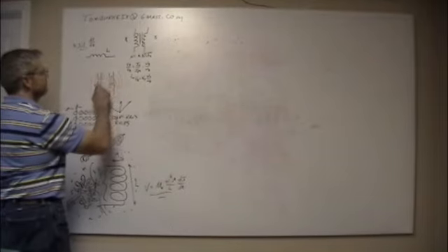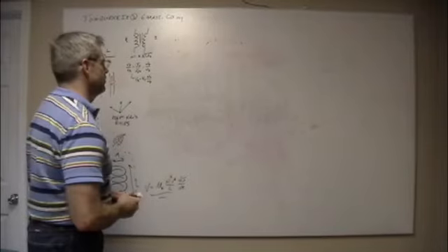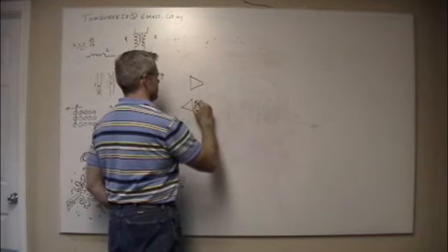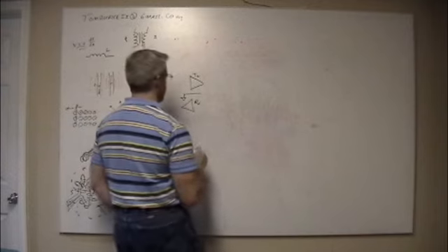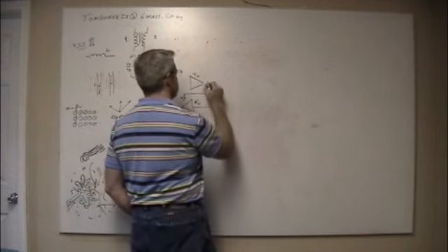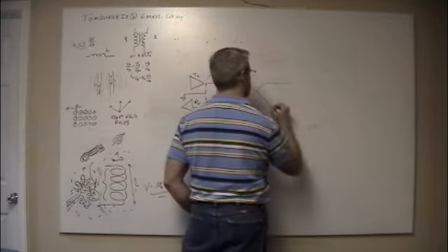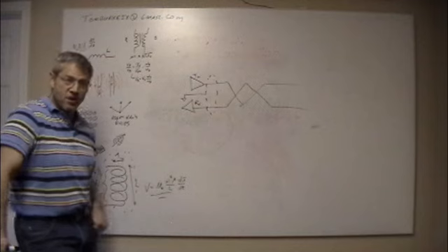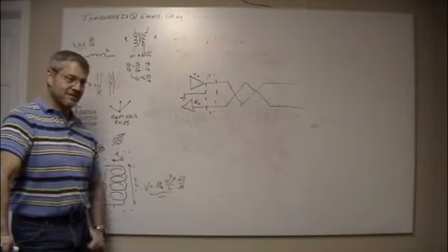So now we've talked about twisted pairs and why you use a twisted pair. And I'll point out something that I've seen done a lot, I won't say where. RS-232 has RX, TX, and ground. And what I have seen people do is tie the ground to a shield and then twist TX and RX together. Now, can you see what the problem with that is? They say, oh, we've got a twisted shielded pair. It's noise immune. It doesn't make any noise. Do you see the problem with that?